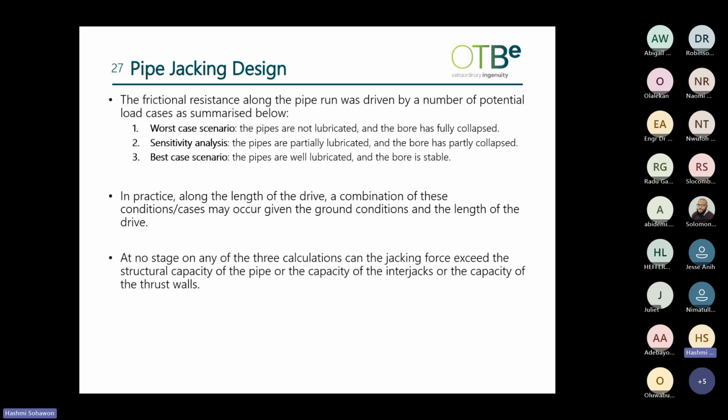In reality, we achieve a mixture of these 2 cases at different sections of the pipeline across the entire length of the drive. So we did a sensitivity analysis in which the pipes are partially lubricated and the bore has partly collapsed. I will go in more detail about this in the next slides.